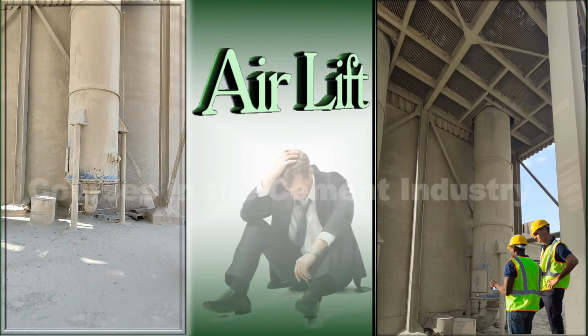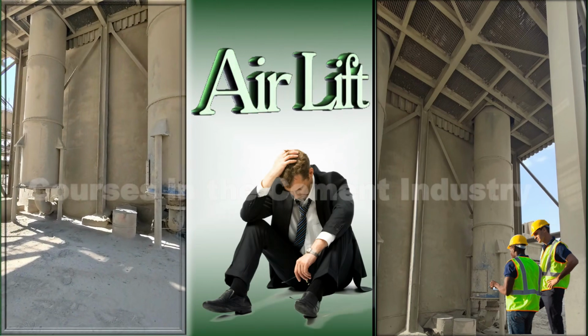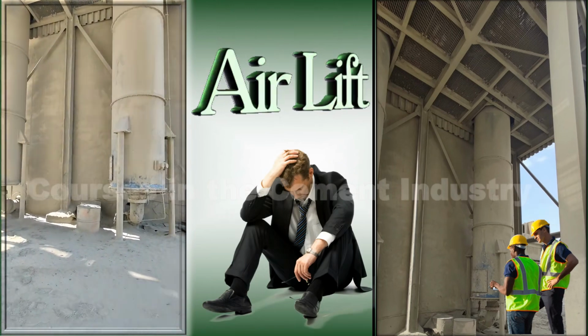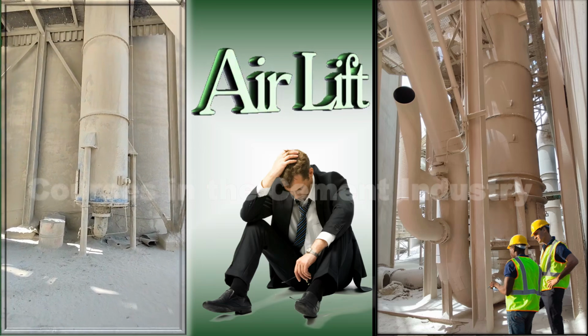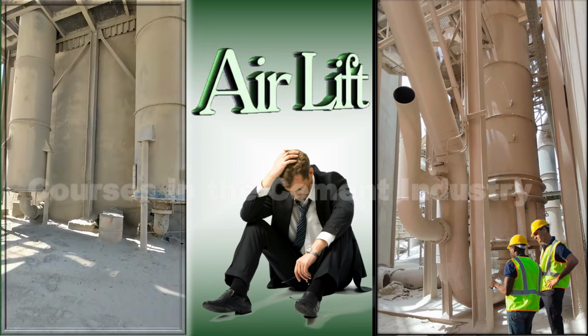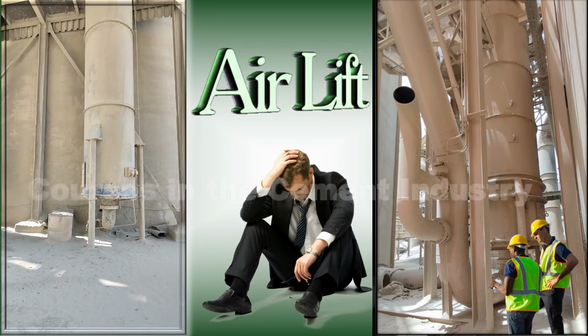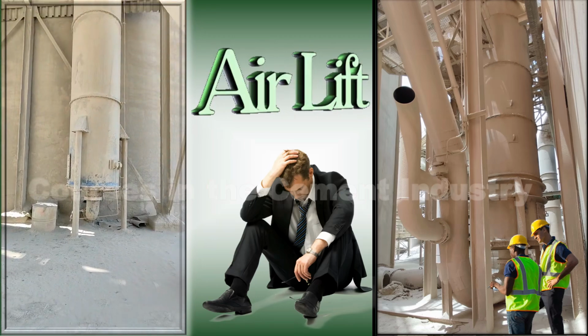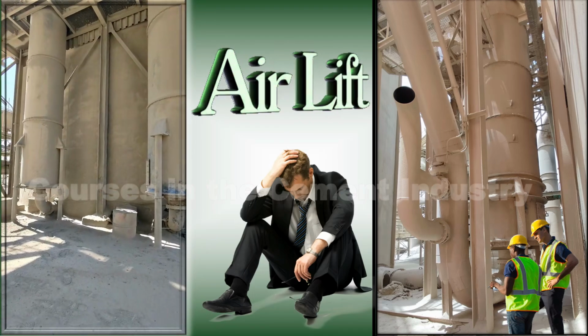2. Airlift. The AIRLIFT pneumatic elevating system conveys dry pulverized materials through a vertical pipe to discharge into receivers or bins at a substantially higher elevation. The AIRLIFT system is suitable for materials which can be fluidized by aeration without segregation. AIRLIFT systems are used in the cement, aluminum, copper, and chemical industries.